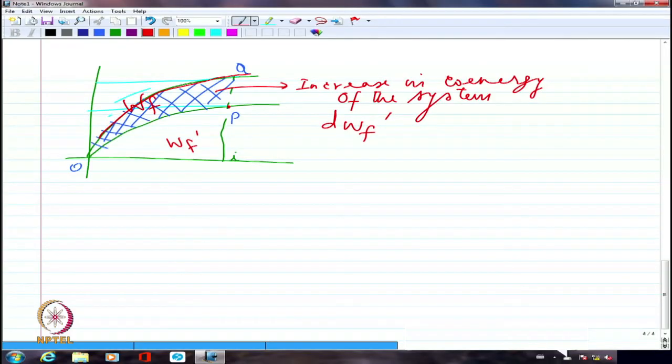Here, even if we consider AC current, we are looking at the RMS value. If you actually consider DC current, you have to again consider the time constant there too. So I am passing a current, let's say it reaches a value of V by R. At that point, you are trying to move. When you are moving, you are going to see a variation in the current instantaneously, but you allow it to settle again and again. I would say it is better to look at an AC current in this case, because we are looking at the induced EMF, d lambda by dt, and so on.